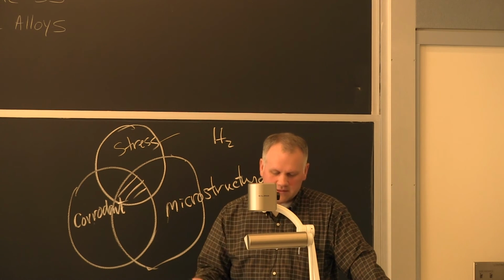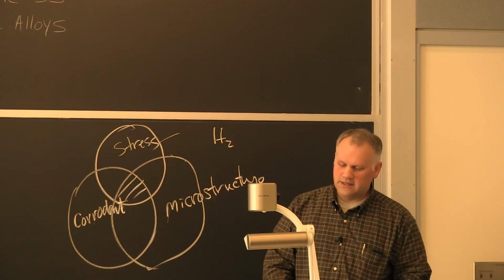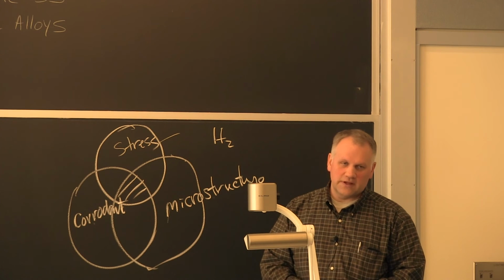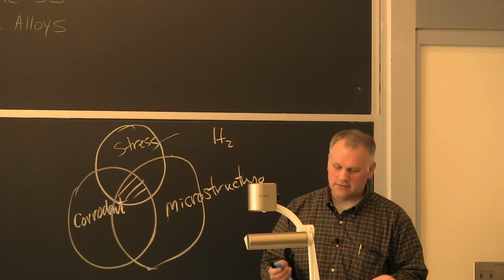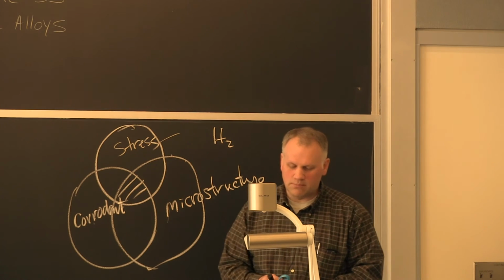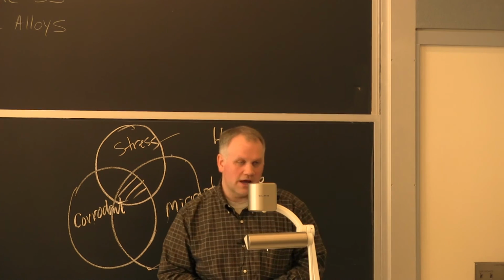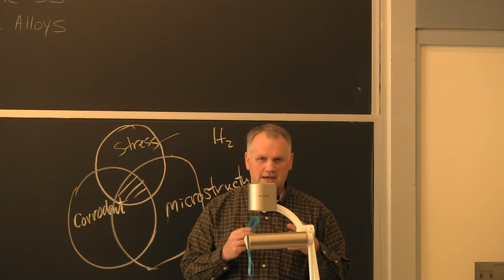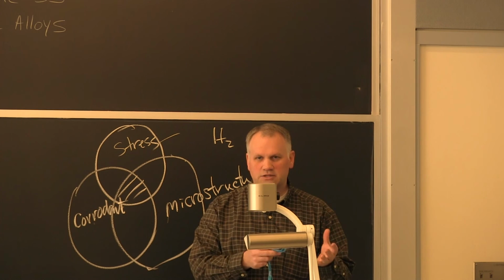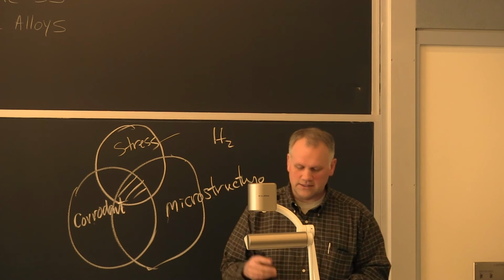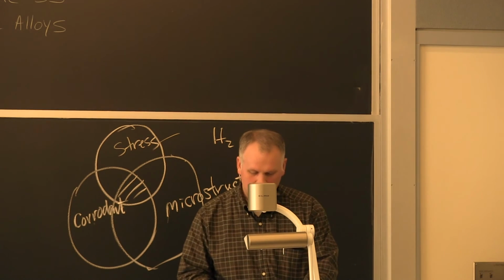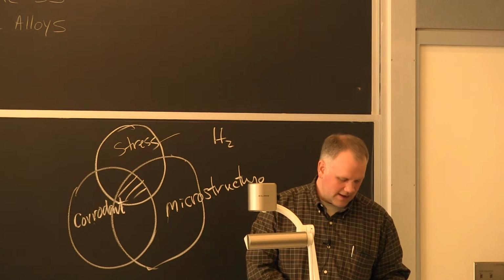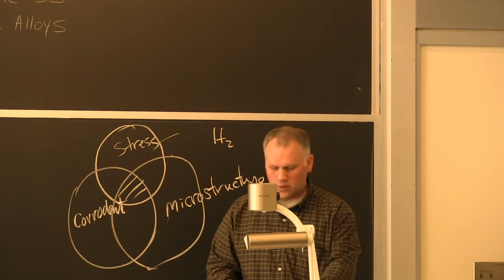Another thing that's often done to control creep properties is the addition of boron. And another thing to keep in mind, especially if you're welding nickel-based alloys, is most nickel-based alloys have not been developed with welding in mind. They've been developed to cast and then machine an airplane turbine or something like that. And welding was not always kept in mind as they were developed. So because of that, we do end up with some weldability issues.